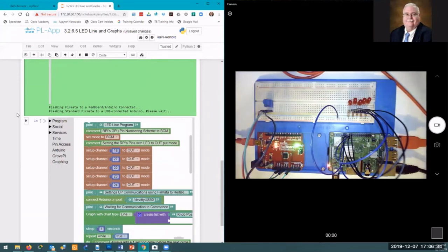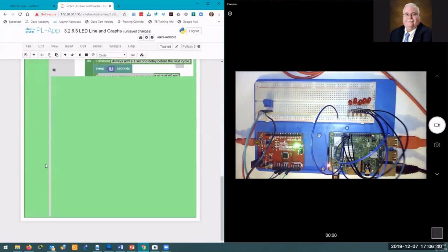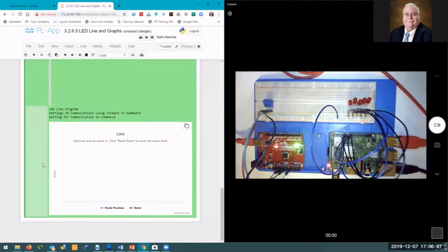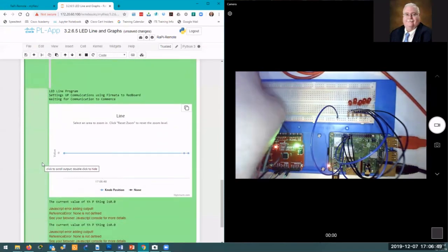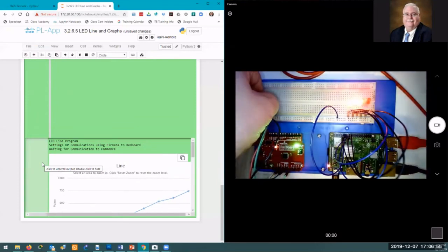When the Blockly code is run, you will see a graph appear below the cell indicating the position of the potentiometer. This will also change the number of LEDs illuminated. Troubleshooting steps to keep in mind: Arduino not flashed correctly, Python program coded incorrectly, circuit errors, or serial connection issues will keep the lab from working correctly.